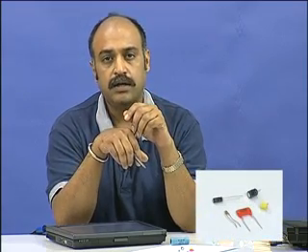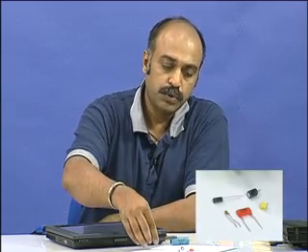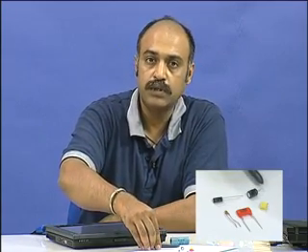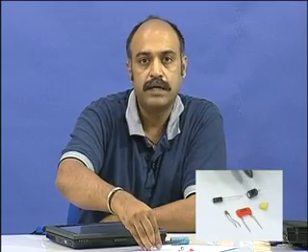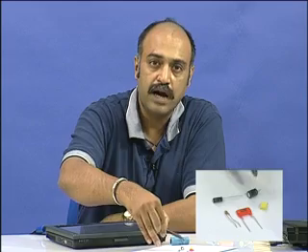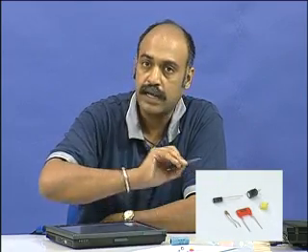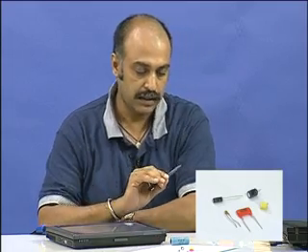The second value that you will see on the nameplate is the voltage that it can withstand, because beyond that the dielectric will break down and it will get damaged. So, you should not apply a voltage to the two terminals which is higher than what is written on the nameplate. Which means that this is a 4.7 microfarad, 100 volt capacitor, and you should not exceed the voltage of 100 volts here.